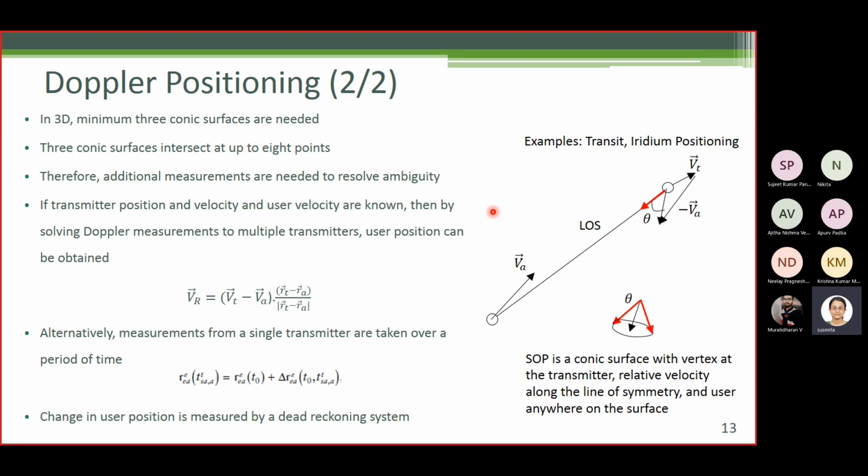So whenever GNSS signals are available, we can calibrate INS error so that the INS can bridge through the GNSS outage period. I've also shared a link to a presentation where you will get to know about a novel application of integrated GNSS INS systems, how they navigate an aircraft through a hurricane using GNSS INS.